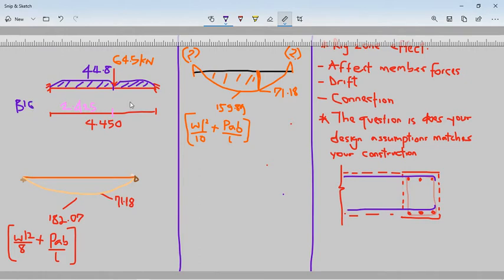So what I did was to calculate the effect of the load manually. Now, I made an assumption for simply supported, and I made an assumption for when the two ends are fixed. So this is the moment I got when I assume it is simply supported, which means that there won't be any movement here, there won't be any movement here.